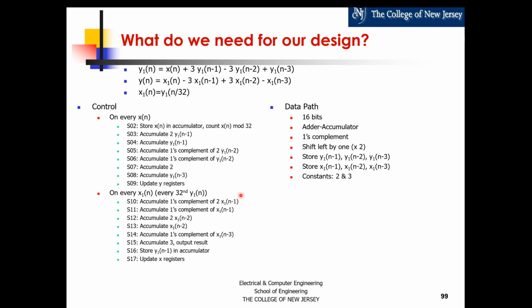because I'm doing that. I need to multiply times 2. Well, I need basically to shift by 1 left. That's a multiplication by 2. That's why I don't have a multiplier to do times 3, because it's easier to multiply times 2 and add the quantity to get times 3. That's less expensive than having an actual multiplier to multiply times 3.